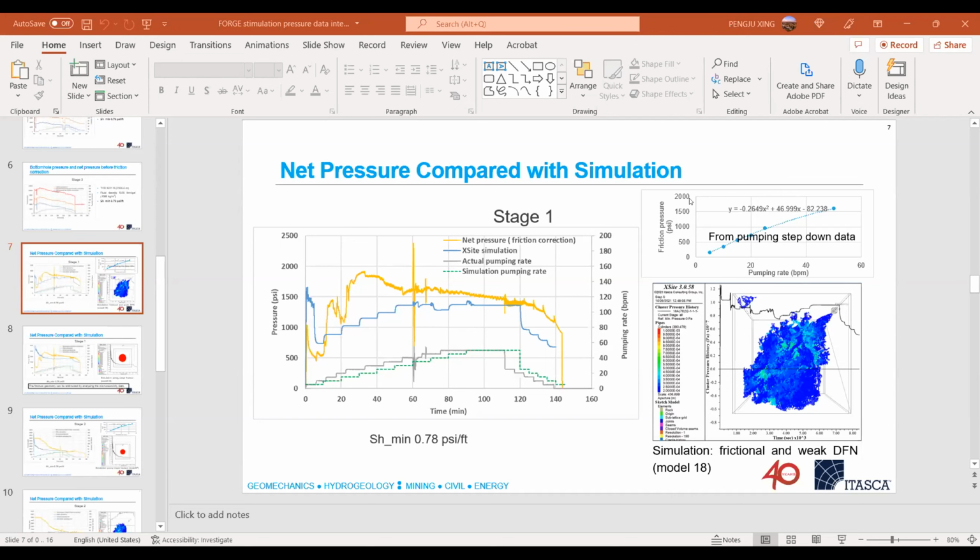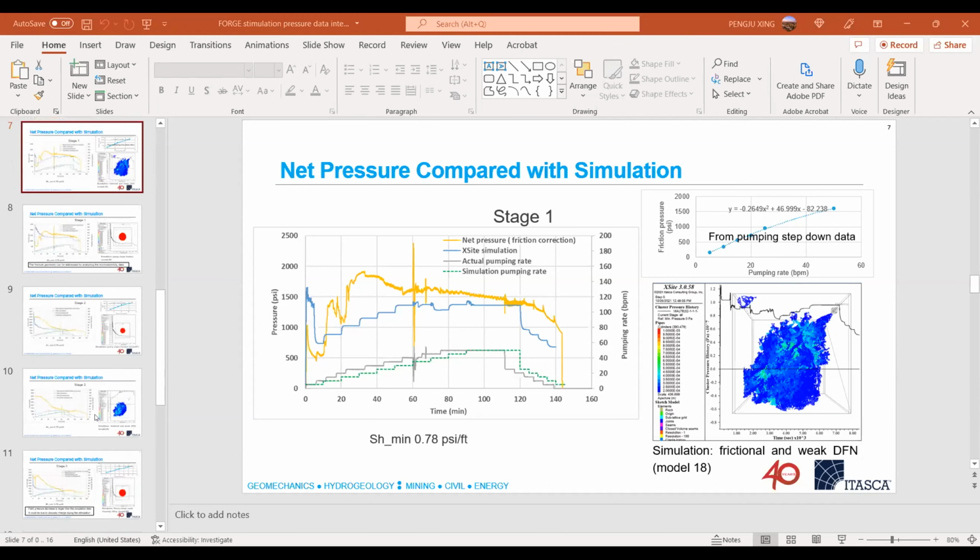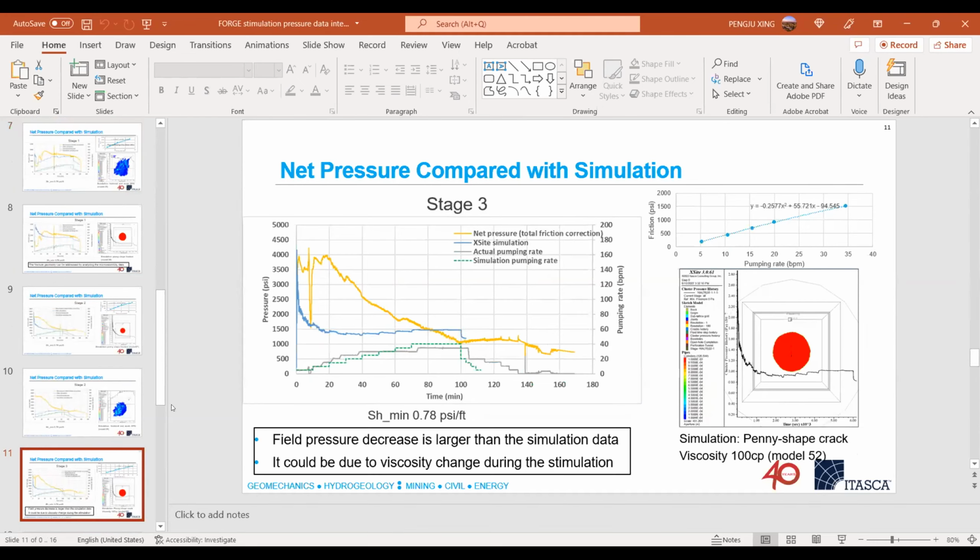John, do you want to go over and answer Karen's second question? Karen, I don't think we know yet, but I think a message to Pengju is that in your bottom hole pressure, you're going to have to make a slight correction for the change in hydrostatic pressure with the proppant, if you haven't already. Okay, I did not consider proppant for the hydrostatic. Yeah. Okay.